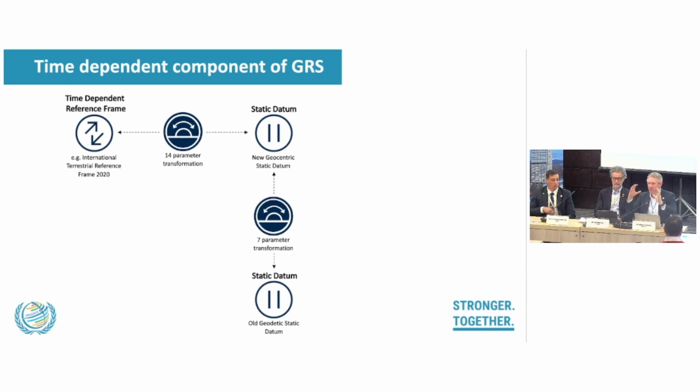It's always giving you the most up-to-date coordinates based on where the land is. It's not a static datum that's transforming back to a common epoch, as we heard about before. So there's this misconception about WGS84 being static and the coordinates never changing. That's not true. So it's something to keep in mind, particularly for countries who keep collecting new data in WGS84. It's always important to reference it back to some common epoch. You can't just keep recording it over time, because you'll end up having different data sets which have different time epochs associated with them.